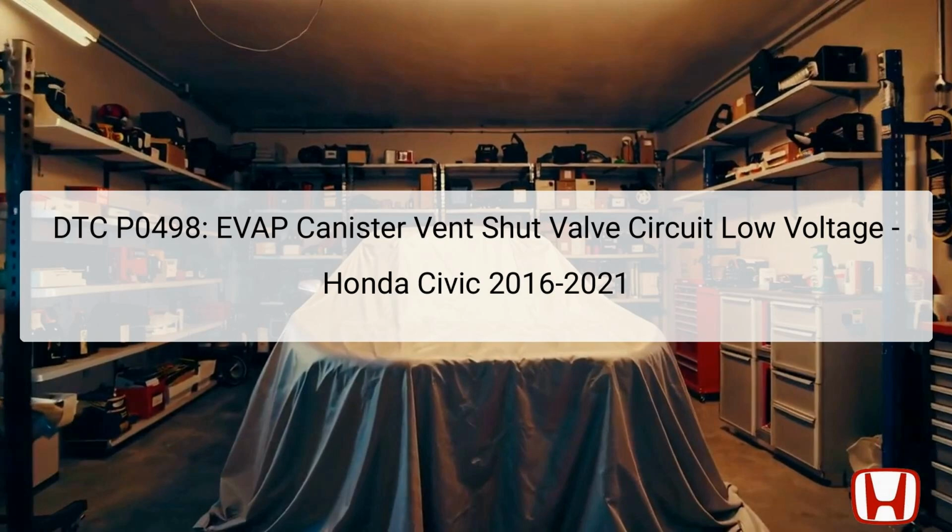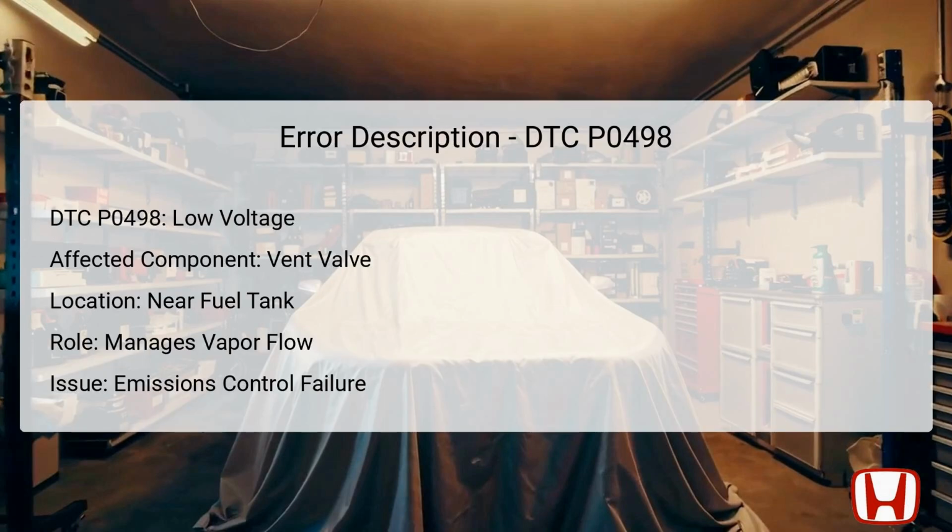The first step in addressing this code involves confirming its presence through diagnostics and using the Honda Diagnostic System, HDS, to gather further information about the issue. It is essential to follow a systematic approach to troubleshooting to identify the root cause accurately. DTC P0498 specifically denotes a low voltage condition affecting the EVAP canister vent shut valve circuit.